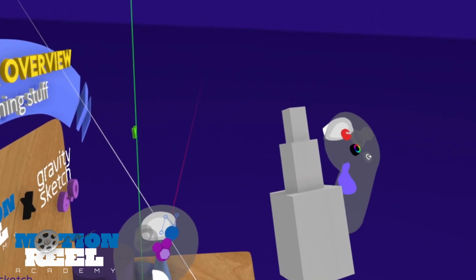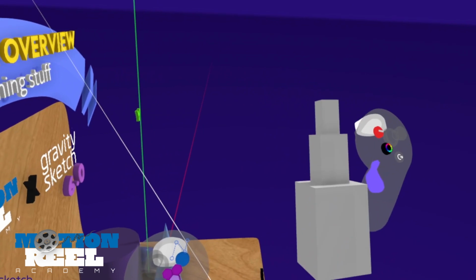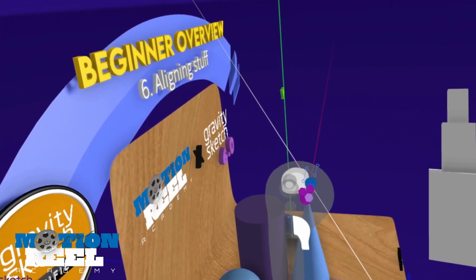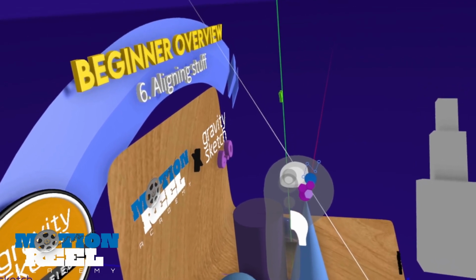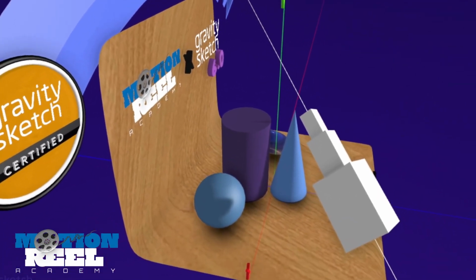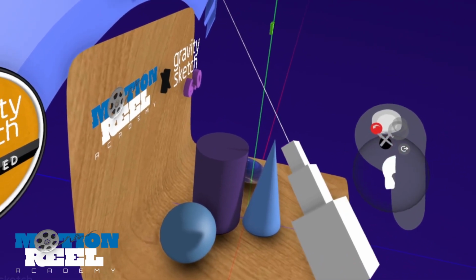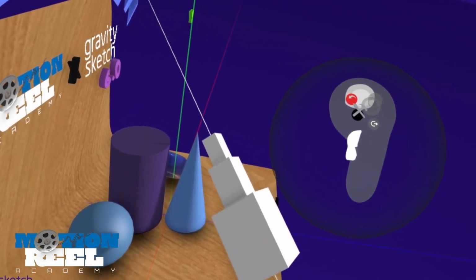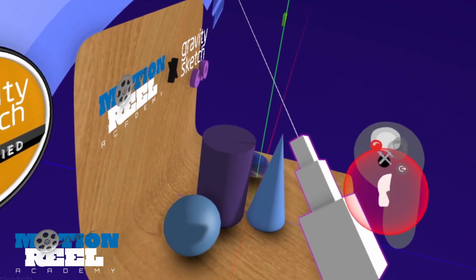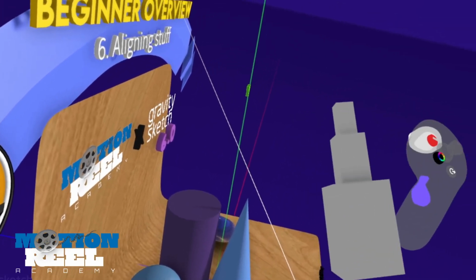Here's the group button. When you have something grabbed or multiple items grabbed, and you're holding the grab button, look at your non-drawing hand and you'll see on the purple button there's 3 hexagons. That's the group button. If you click that, it will group the 3 items and send them back to their original spot. Now when I move over this item with my grab sphere, you'll see that it turns purple instead of red. Purple items are groups of items. So you'll see the purple line around this, and that is now a group.